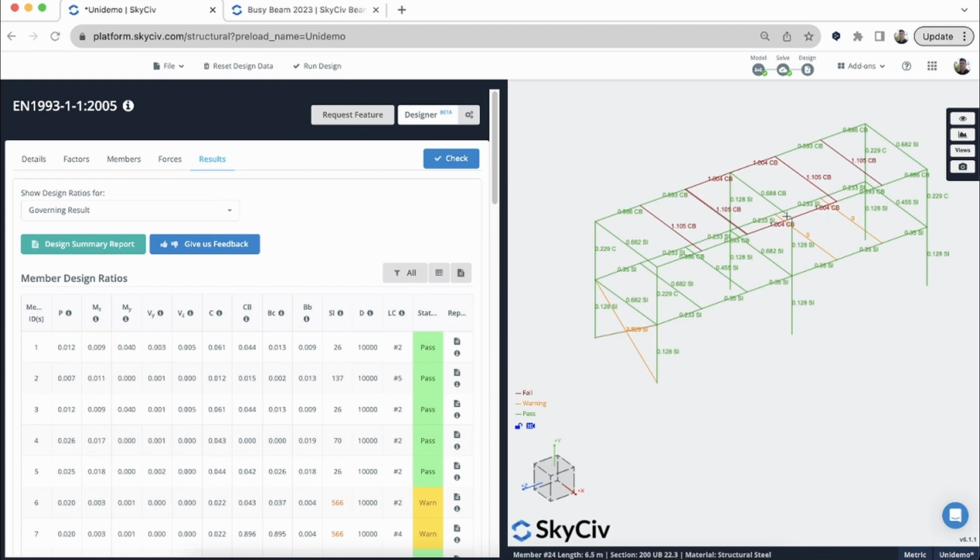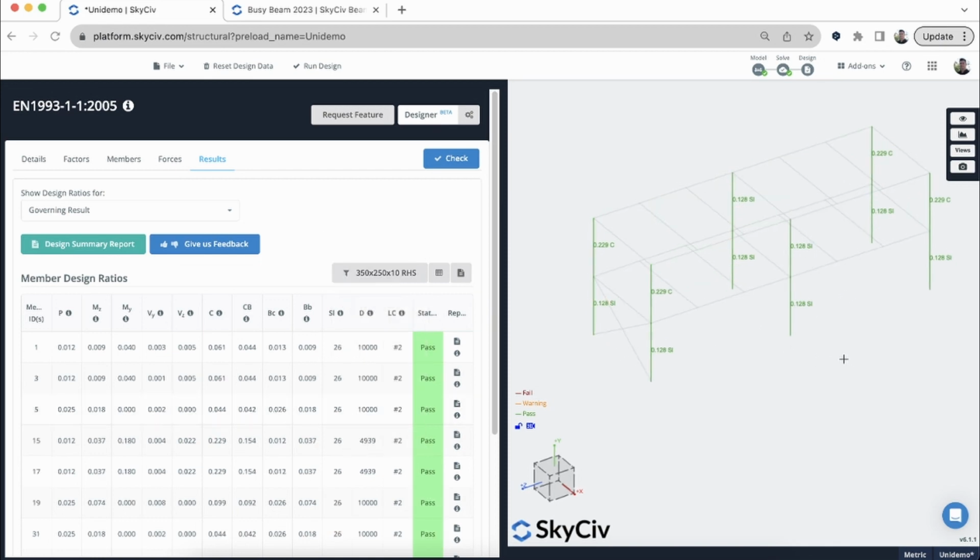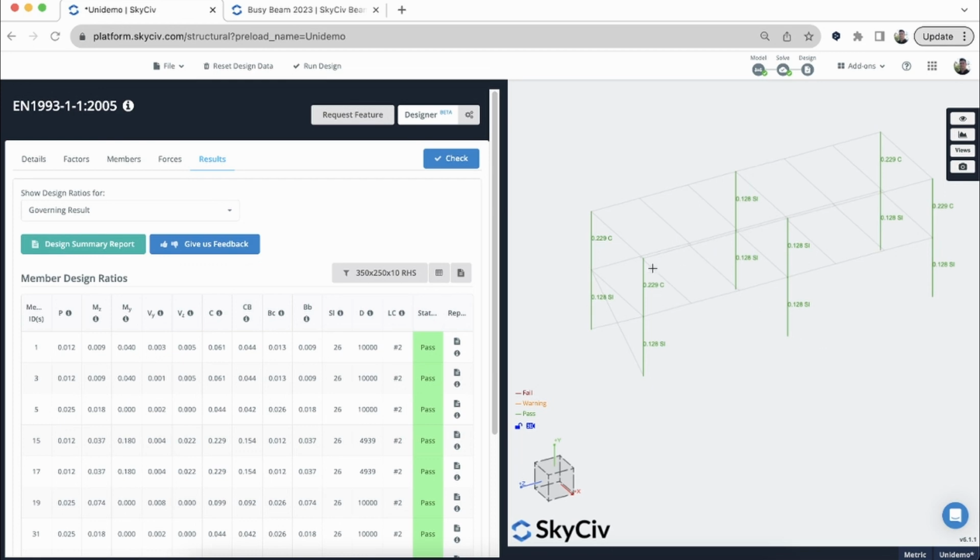So we want to be designing the I-beams, the angles, and then we can also look at the columns, which is these RHS. And we can see they're only about 23% utilized. So we've got wiggle room there where we can improve the design by reducing the material usage or the amount of material in the section, and increasing that utility to somewhere closer to 1. So we've got some kind of wiggle room, we've got some space to optimize for these columns.